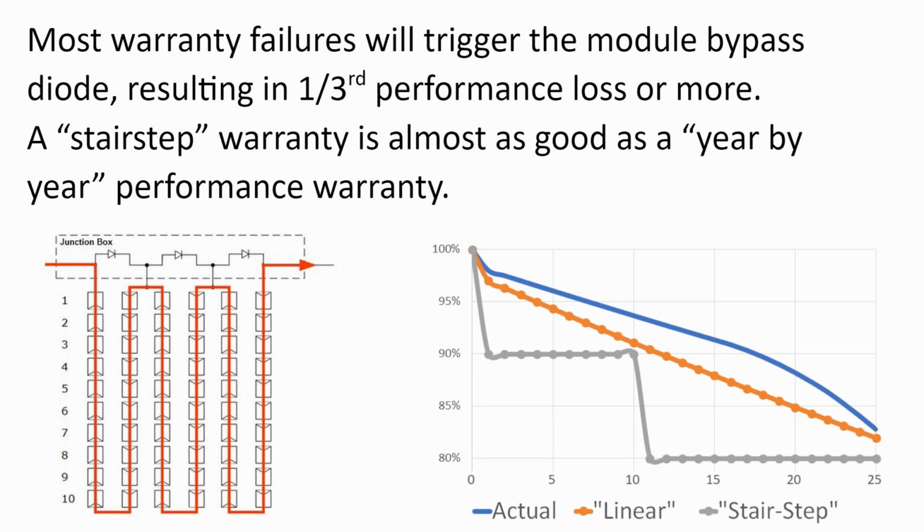You could use a thermal imaging scanner to see a hot spot on the panel that would reflect open circuit voltage, which would reflect a popped soldered connection. But you wouldn't be able to just look at the panel and see, oh, there's a wire that's not connected in there. So the problem is if your installers are too rough on the panels during installation, what they'll be able to see is that there's a loss of 1/3 of the voltage that should be there, but they won't be able to see it for themselves with the naked eye.